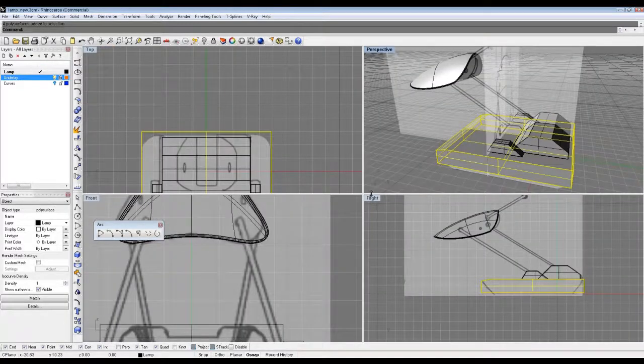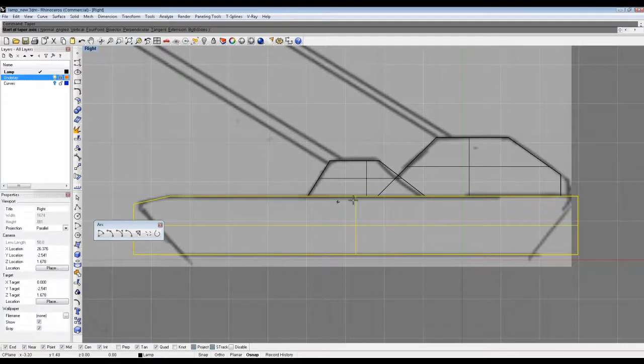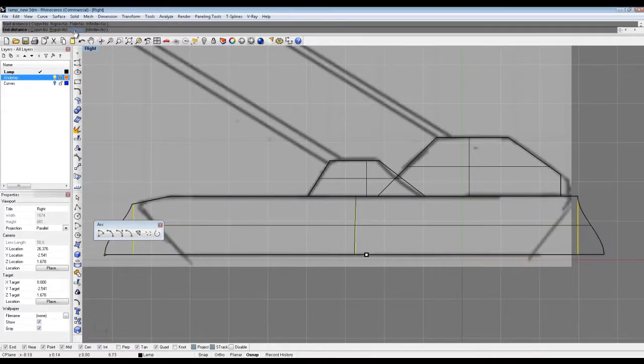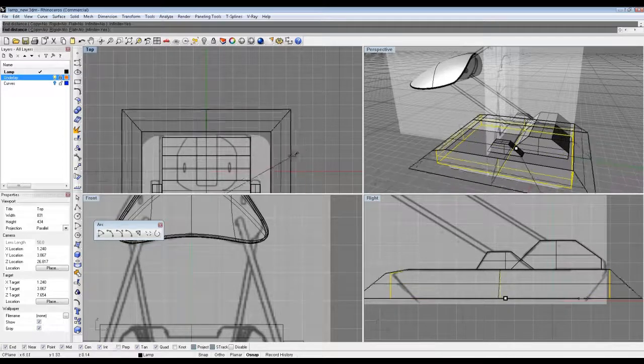We've got a taper down here at the bottom. Rhino's got a great taper tool. So I'm going to taper this. Middle's turned on. We'll taper it from there to there. And I'm going to turn infinite on. And now what this did was, you can see in the perspective window, it's actually tapering that how I need it to be.